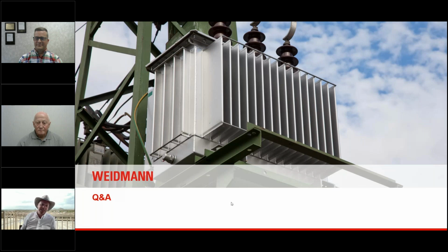So getting those out of the way, now, Kevin and Aleksandr, I'm going to have to ask you the questions that are coming through right now. One of the questions we had is, with DPE, it's clearly possible to increase the thermal class between layers, but what are the alternatives for cooling ducts for high temperature insulation systems? Something here saying cooling ducts are manufactured with pressboard, that is not a thermal upgraded material. So with the mix, is it possible to achieve a hybrid insulation class 140 with a top oil maximum of 65 degrees C?